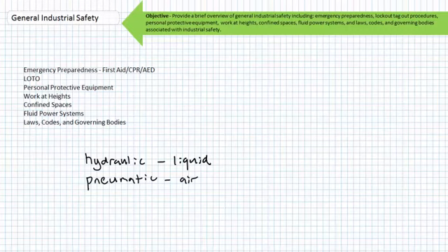Liquids and gases under pressure can do a couple bad things to a container or a hose if the pressure is too high and the container or hose are damaged. 1, the container or hose could catastrophically rupture, or 2, a pinhole leak could develop. The pinhole leak is especially dangerous in the case of hydraulic systems, because that thin jet of high-pressure oil is now a poisonous laser. If one was to cover a pinhole leak with your bare hand, you might lose a finger in the process or be subjected to something called an injection injury.